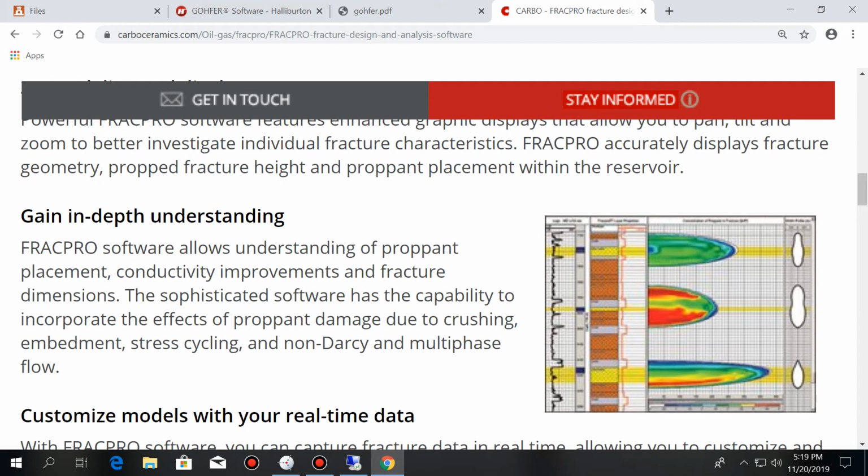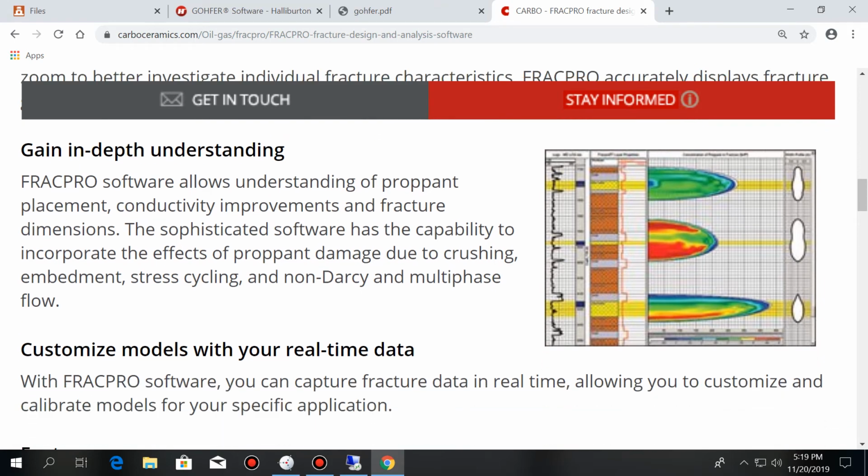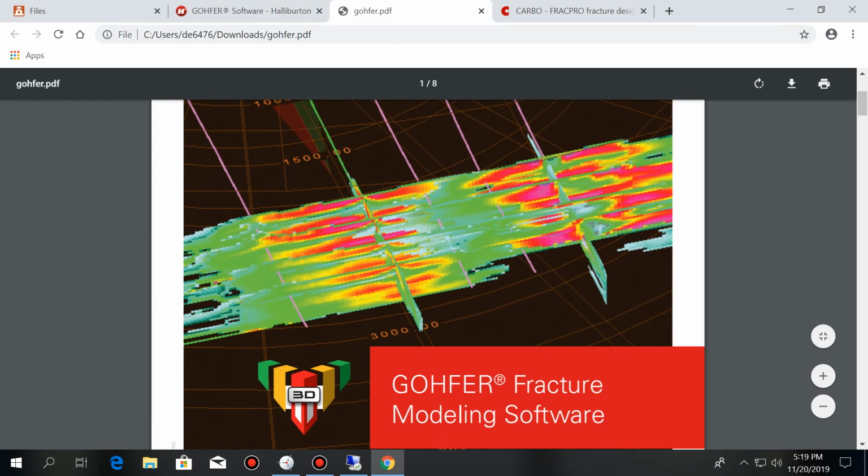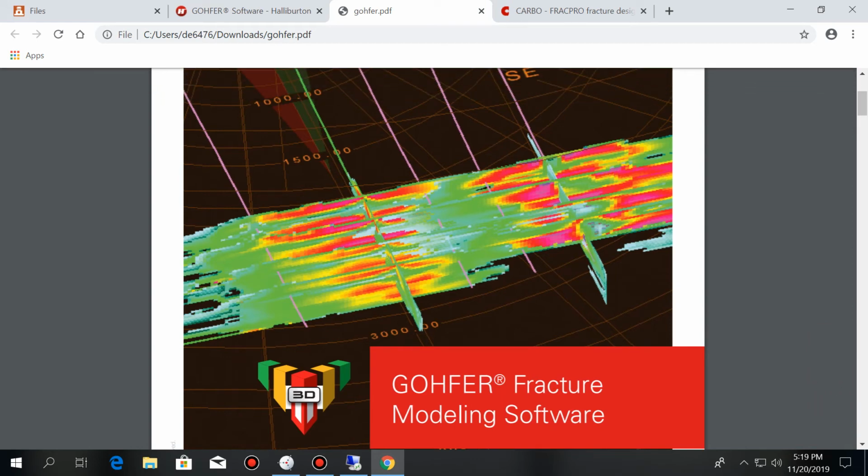And if you want to go a little bit more complex, this one is just for one fracture. I think this software also solves problems with several fractures. Coming back to the previous one, when you have several fractures, fractures may start to compete with each other, and now we cannot assume anymore these conditions of far field stress or just one single fracture. You need to take into account the stress that the other fracture puts into the medium.